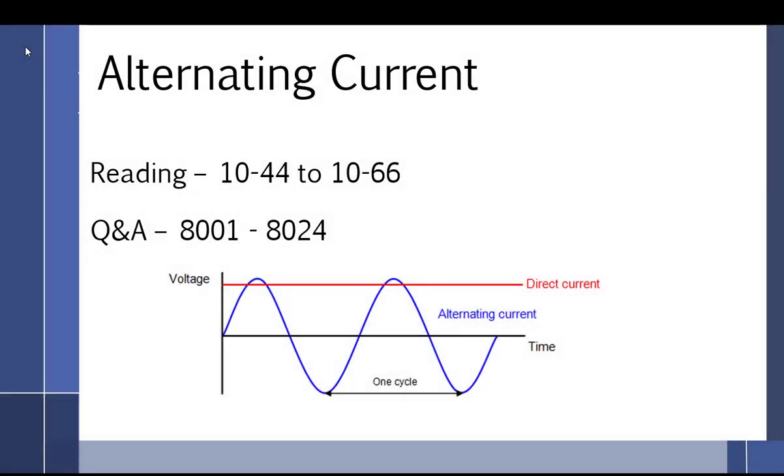All right, alternating current. Well, first of all, I like my little drawing here. Direct current looks just like that on an oscilloscope. It's just a line going straight. Doesn't go up or down. But alternating current goes positive then negative, then positive then negative, and positive negative. It periodically changes direction. So this is one direction, this is the other, and it continuously changes in amplitude. This is the amplitude. See, it's constantly changing, and this is time as we go.